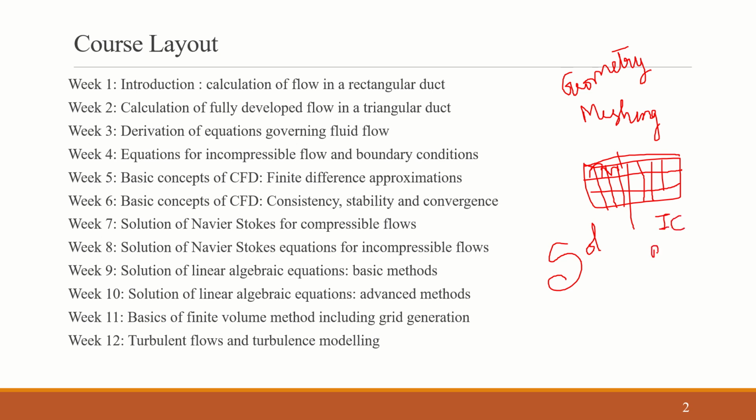and boundary condition. Boundary condition is nothing but along the boundaries of the system, we should know what condition is being maintained. As I mentioned, at the inlet we have velocity as this, and the outlet is open to atmosphere, and the surroundings, all the rest, is covered with wall. So we are using no slip boundary conditions. Those types of things we are giving, and after giving the initial condition and boundary condition, we are using solvers and getting the solution for that.